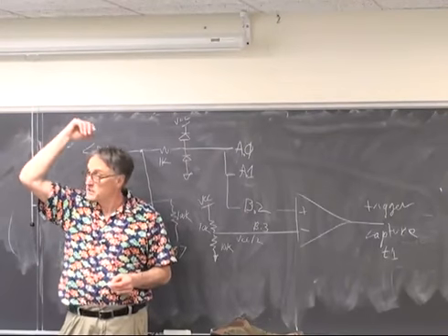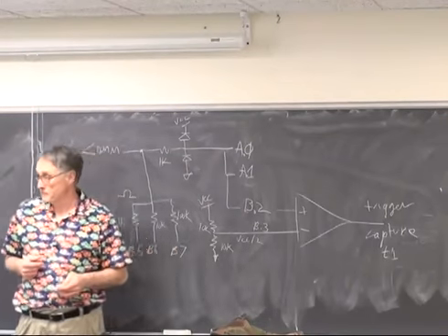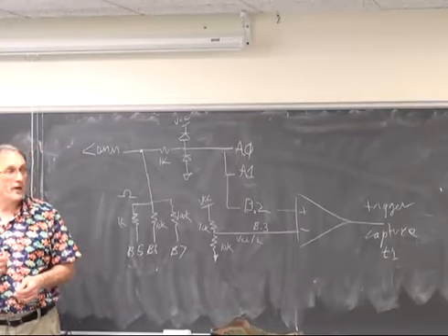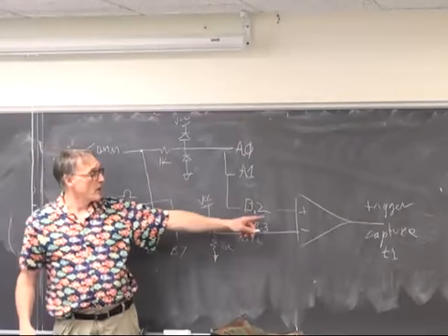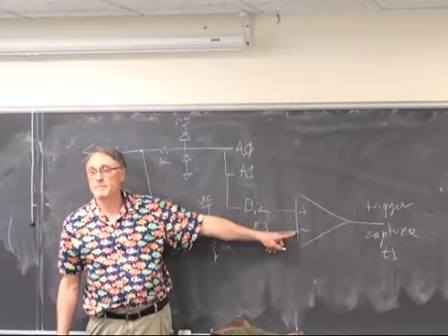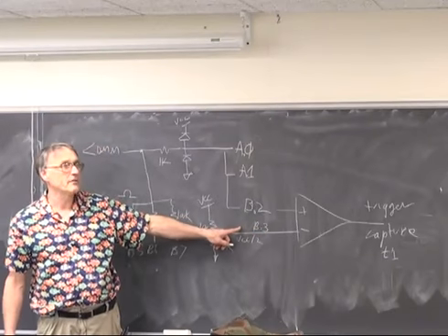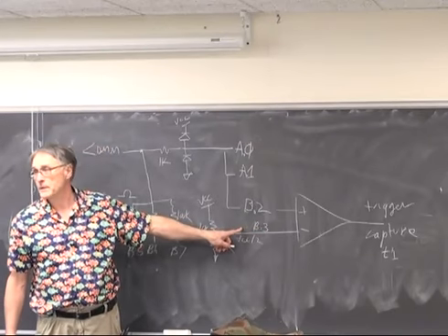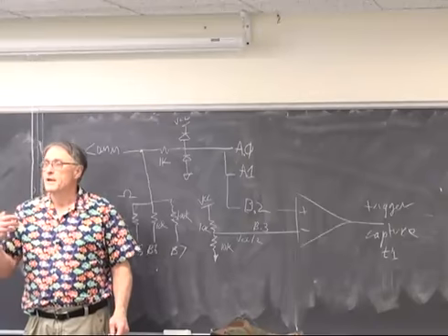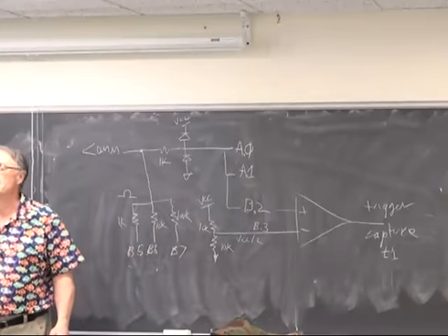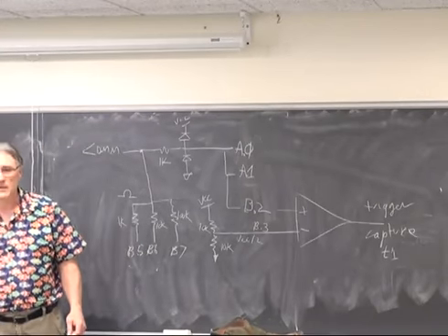Change the divider, change the clock divider, the prescaler. Right, so for very high frequencies, you're going to want to run the prescaler at a divide by 1. For very low frequencies, you might want to run the prescaler on a divide by 1,000, so that you always are counting up a reasonable number of ticks.